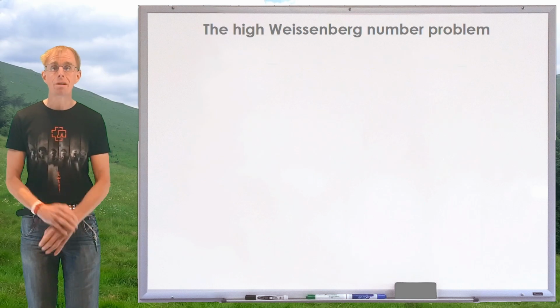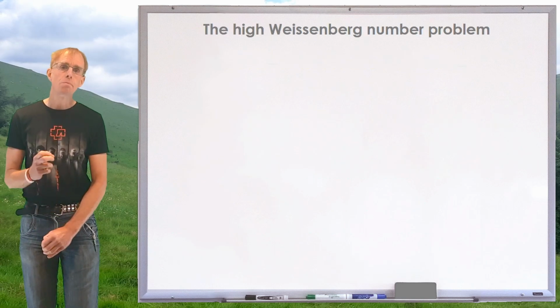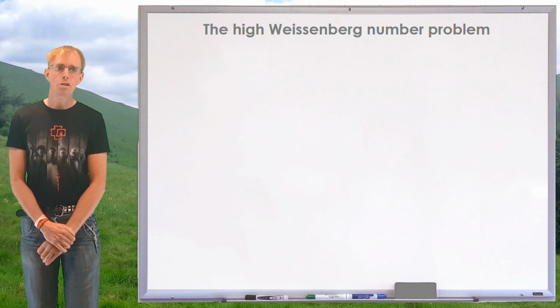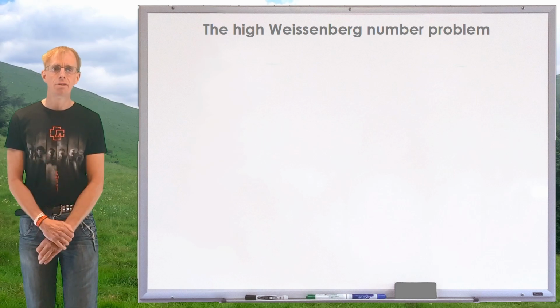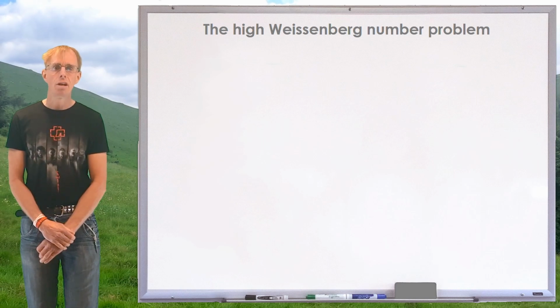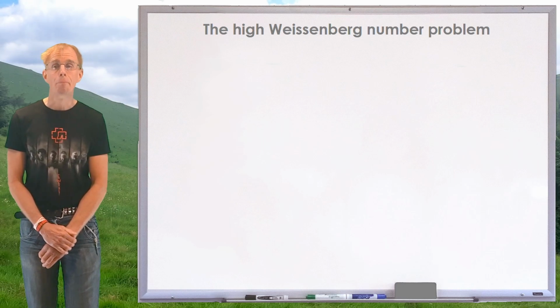So let's talk about numerics. Let's talk about some of the problems that you're likely to encounter with numerics. And the key problem that dominated the field for a number of decades when it comes to viscoelastic flow modelling is called the high Weissenberg number problem.